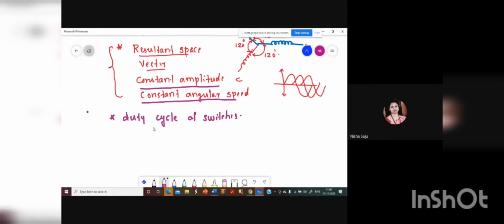If you compare with sinusoidal pulse width modulation, there we use a control signal and a carrier signal, and then you take the different pulse ranges. Okay, you can take it that way. But in the case of space vector modulation, this will always calculate the duty cycle of the switches to synthesize a desired output voltage on an average basis.